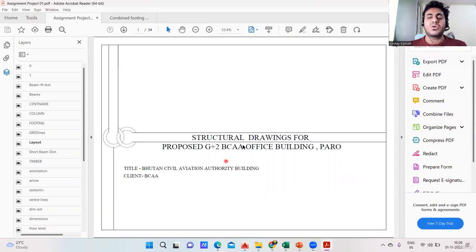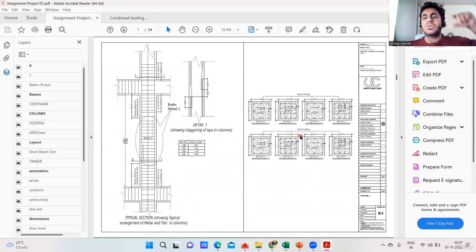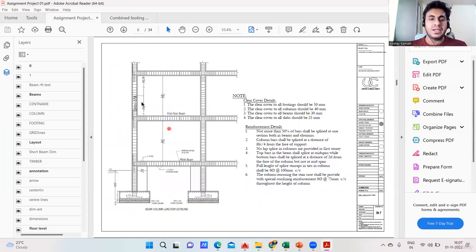And here, can you find the column height? It's very simple. Because we are done up to the plinth beam bottom and plinth beam top, we have taken the column. And again, from there, from the plinth beam to the ground floor, to the first floor, to the second floor, because it's a ground plus 2-story building, isn't it? So G plus 1, so again you have to take 2 times whatever your floor height is. If it is 3 meter, you multiply it by 2 times, so that you get the first floor and the second floor height.